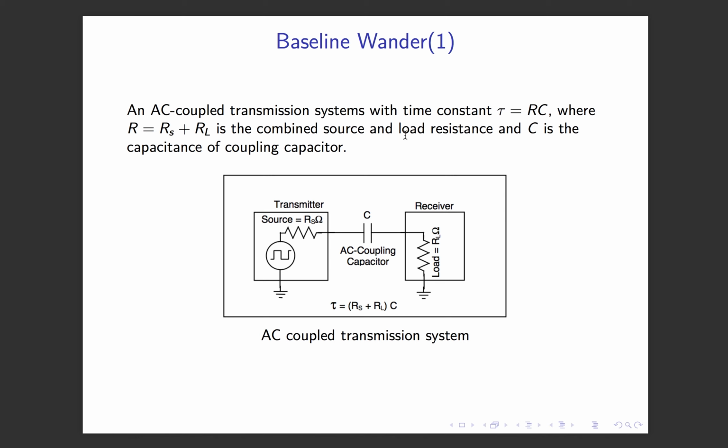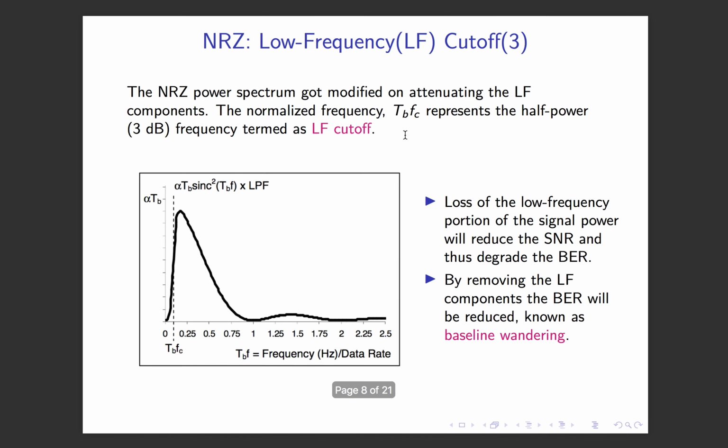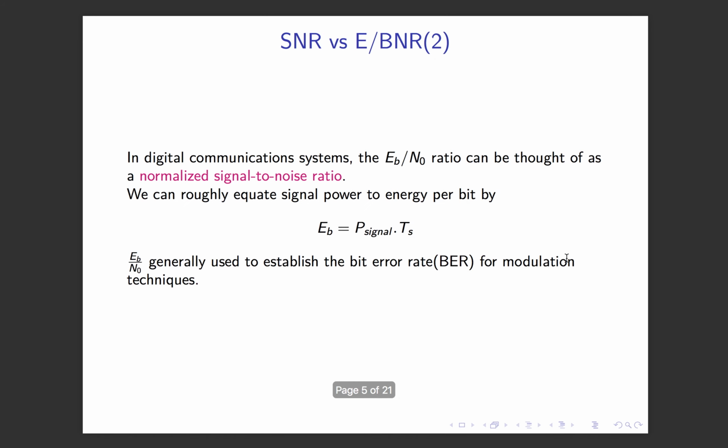And one thing we should go back to, I really missed that. What is the real expression of BER? Here I have mentioned BER equals Eb by N naught, but for AWGN noise, the BER is roughly 0.5 times the error function of the square root of this term. You can check the text; this is the expression of BER.